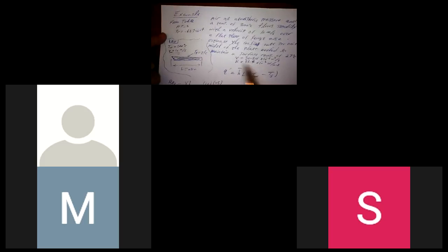You can go to this table, based on 300 degrees Celsius, and find the kinematic viscosity, and then the thermal conductivity if you need that. Do we need the thermal conductivity here? Yeah, we need it.